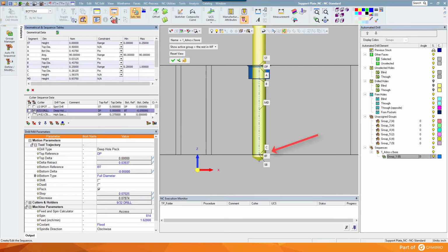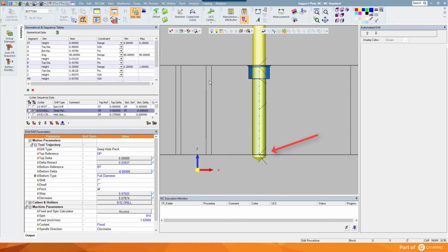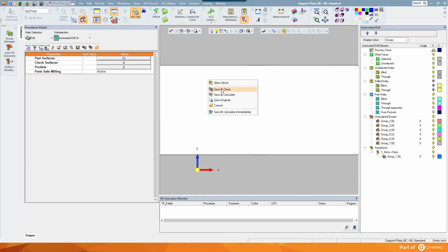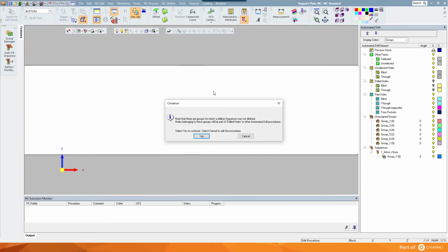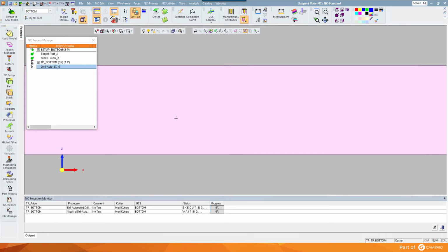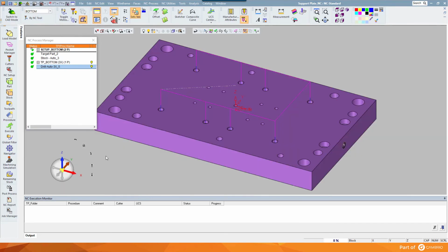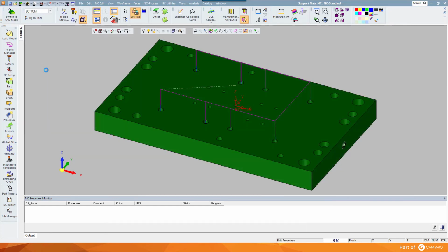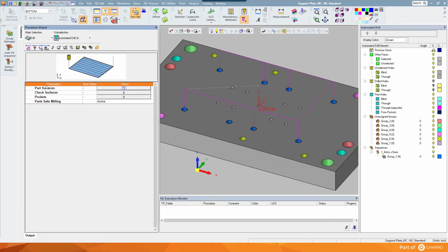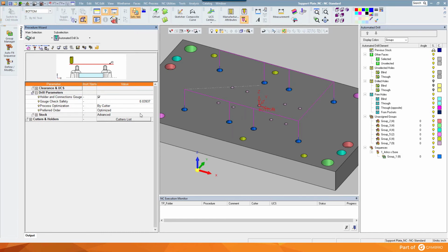Notice the system used the anchor BT to define the bottom depth of the 9/32 hole. The ranges were set to allow the sequence to drill and counterbore the hole, if the hole depths were within the preset standards. The user has the ability to open the ranges for any of the data fields to allow for minor design variations. Users have options to control tool ordering based on each tool or by each sequence.